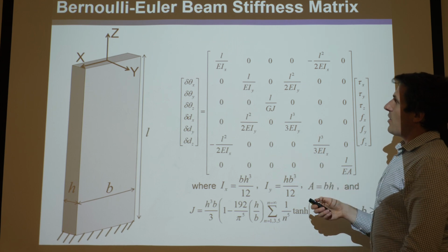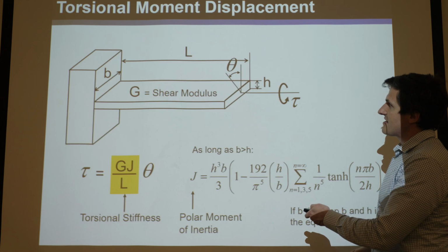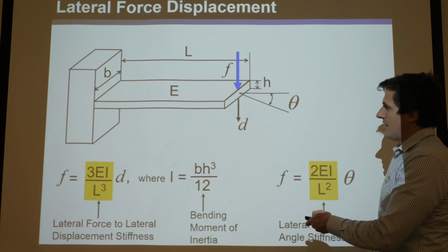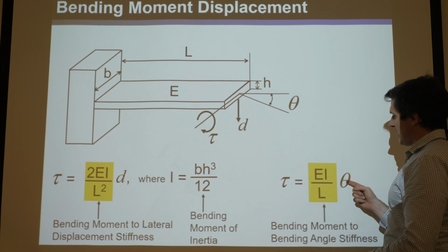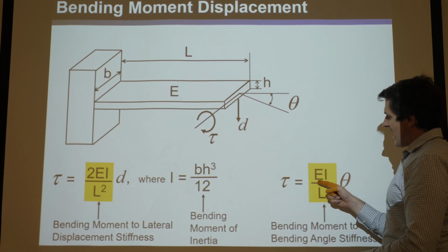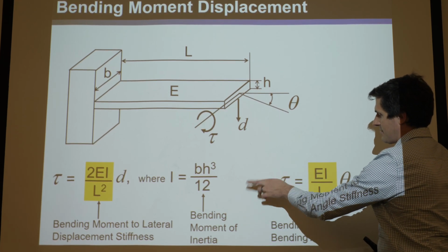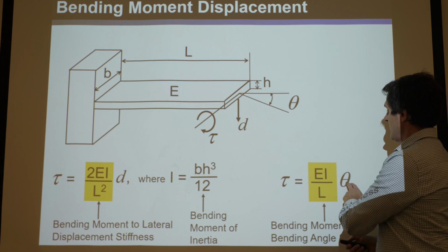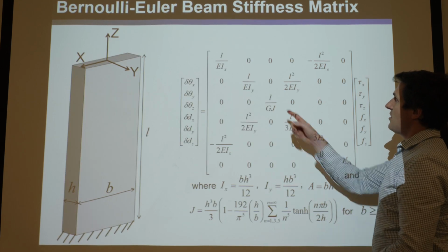And if you look at the bending equation that relates tau to theta x, let's go back here. Yep, tau to theta x, it's EI over L, which we're going to flip so it's L divided by EI times tau is theta here. For bending, notice this is the bending case, then you'd see this is correct.